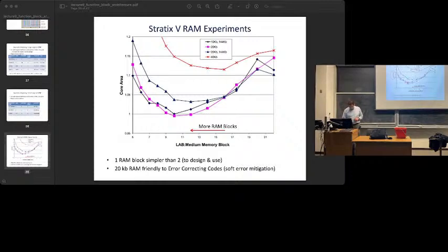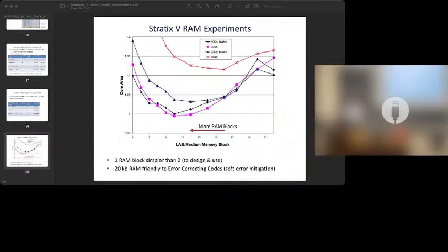The other question is why 20 kilobits? First, 9 seemed kind of weird. Why didn't you use 8 but use 9 instead? And now instead of 18, you're using 20. Why the weird numbers? It's basically for parity bits. A lot of FPGAs use 9 kilobit or 18 kilobit RAMs instead of powers of 2, because people often store parity bits in the communication industry.